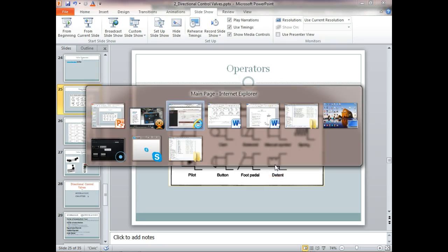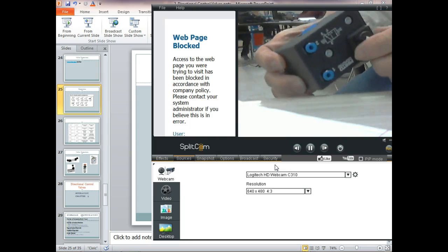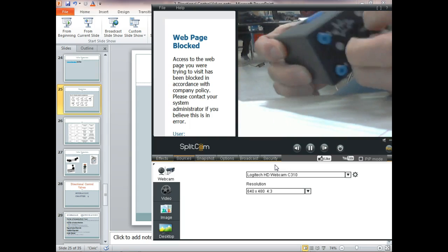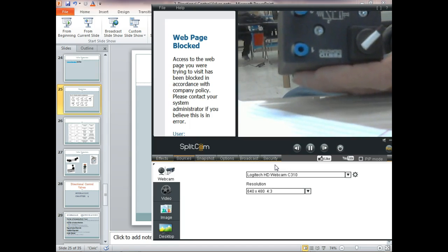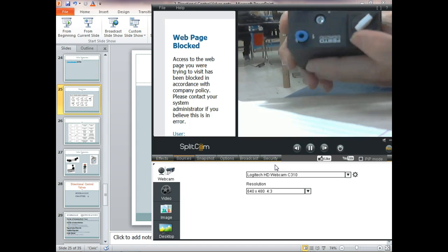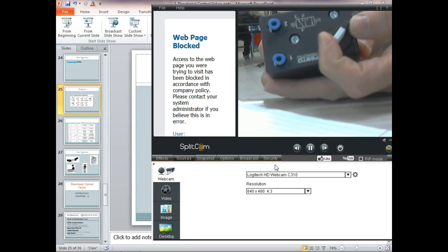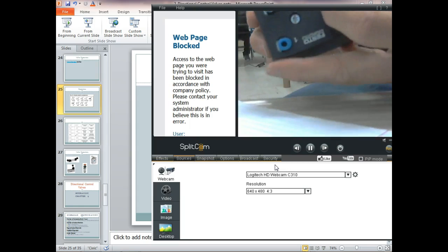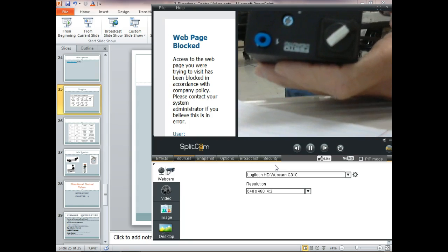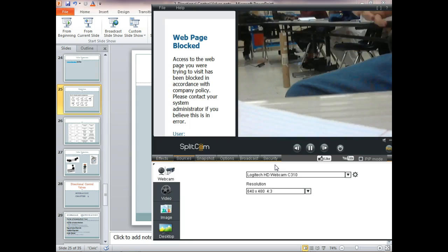What we see on this one is I have a selector switch on the front of it. When I turn it, it stays in that position. So that's what the detent does, right? It keeps it in that position. And it's spring return, so as soon as I move it out of the detent just a little bit, it should flop back over into the position. But as long as I leave it right there, it's going to stay there forever. That's what the detent does. It holds it in a position.